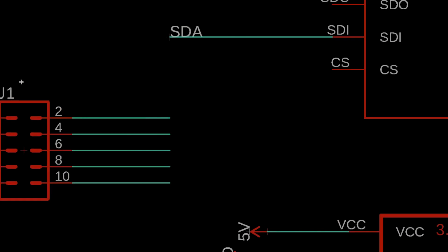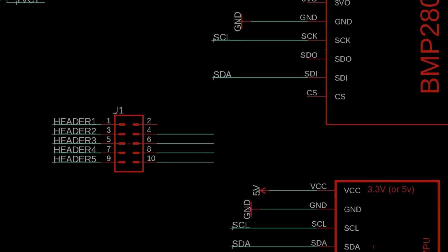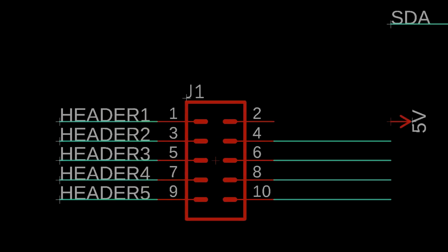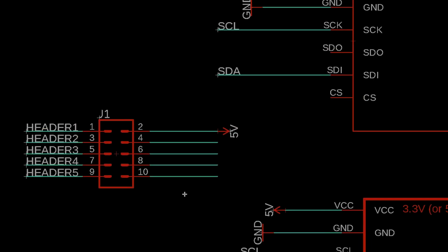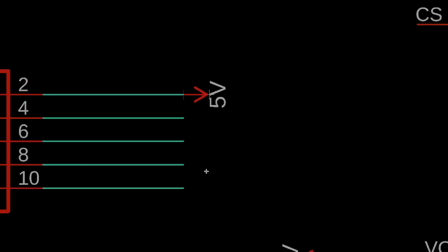These are less customizable pins, but they do continue to add more functionality to this computer. So the first 2 here, we're going to do the top one. The top one is going to be, let's see, I think this should be 5 volts. So let's actually delete the thing here so that we can connect that little 5 volt pin to it. So we're going to go ahead and do this. And I'll connect that to 5 volts. And then I will connect this to ground. And there we go, so that when you break out something and you put an extra sensor or something like that on here, you basically want to be able to have a common ground and a common 5 volt line.